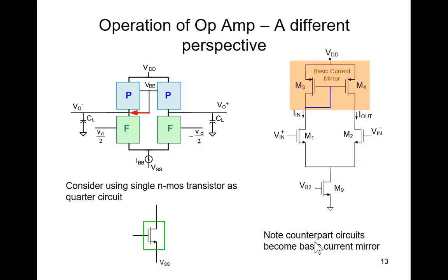So don't forget that idea. We're going to come back and look at things to do that with. Right now, by creating this as a current mirror, we haven't touched the output conductance. The output conductance of this circuit is the same as it is if we put a DC voltage bias here. The reason the conductance is the same is we haven't changed the quiescent current. Tail current stays the same. If the tail current stays the same, the output conductance here stays the same, and the output conductance here stays the same.